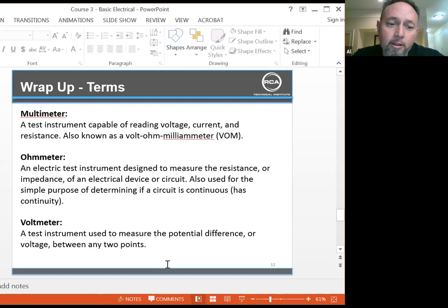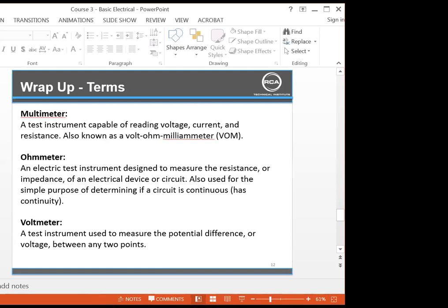So one of your best practices should be to turn the circuit off, make sure you're ohming out correctly the way that the circuit functions, and then turn the power on and do it with the power on, because it's always safer to test with the power off. You can't test everything with the power off, but do as much as you can without that circuit energized. The basic understanding for ohms is if you're dealing with a switch or a load, guys. When you're ohming a load, you should see resistance values there. Depending on the state of the switch is what your ohm meter will read. I know when guys start using their ohm meters, it's understanding the difference between ohming a switch and ohming a load.